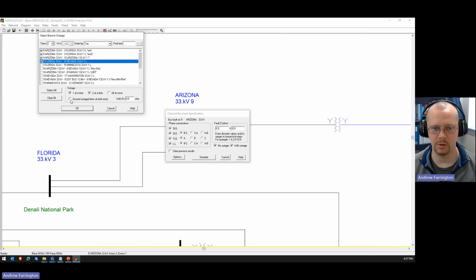If they were going to be working on the line, a lot of times they'll open the line up and then have switches that are visually open so that they know that the line is de-energized, and then they'll hang grounds on each phase, ground conductors from each phase to ground, so that it's clear to the people working on the line that the line is dead.